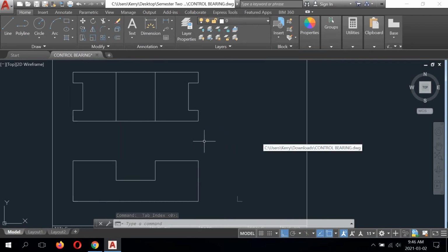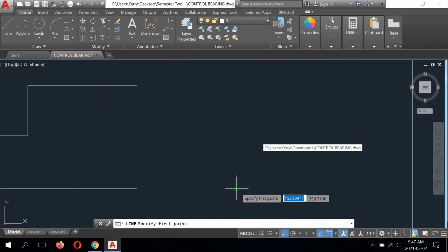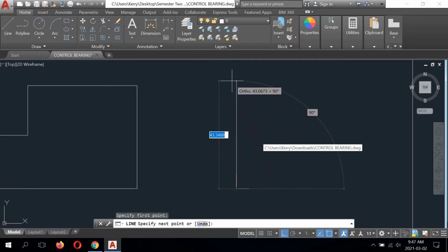Alright, we've got one more view to work on, which is the right side view. So we're going to grab our line command again, zoom into the last origin, pick up the endpoint in the same position you're used to, and we're going to come up. This should be no lower or higher than this line. So we can type 41.5 or O-track it. If I O-tracked it, you can see that green beam horizontal line, and it's previewing 41.5 for me. So I'll just